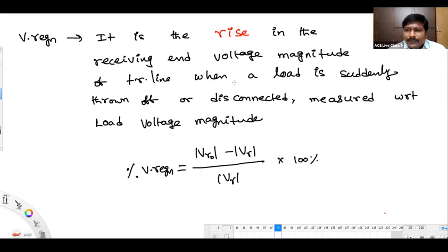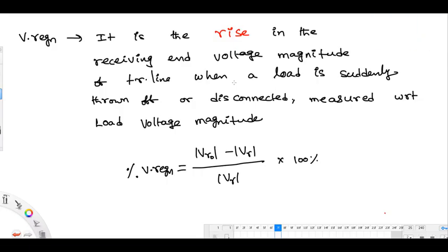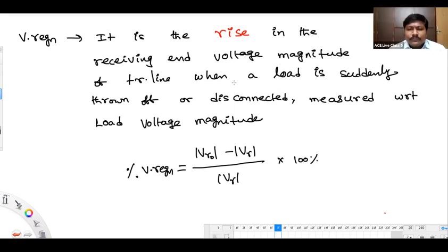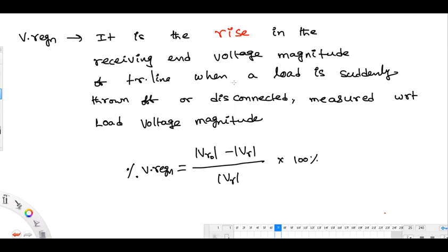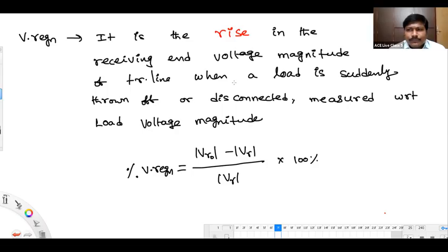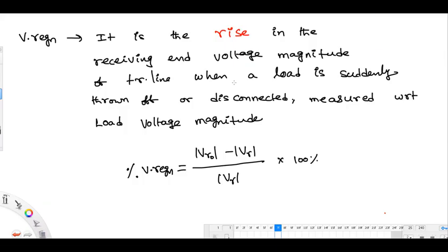But in some problems I have seen that the circuit breaker is connected across the capacitor, and the transient recovery voltage is calculated on the basis of only LC oscillations or an RLC circuit.